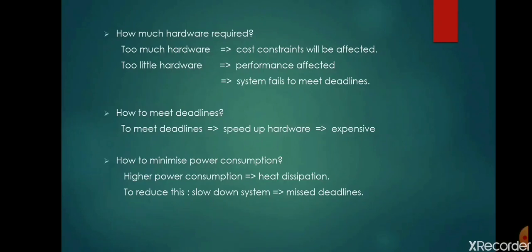The embedded computing systems we use do not actually come with a keyboard and screen, so it is very difficult to know what is going on inside the system without affecting its operation. We must continuously look at the electrical signal values on the microprocessor bus to know what is going on inside. And in real-time applications, it is very difficult to stop the system to understand what is going on inside.